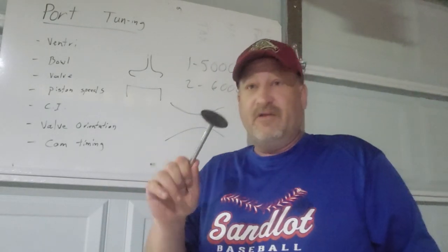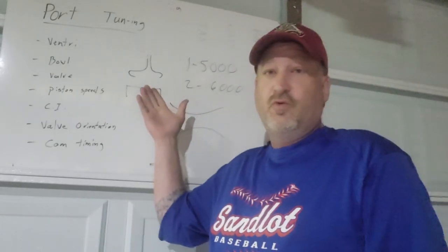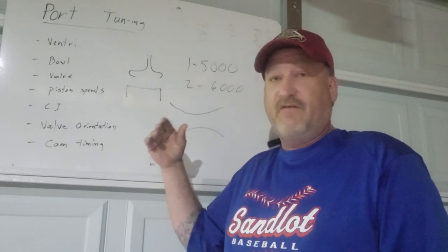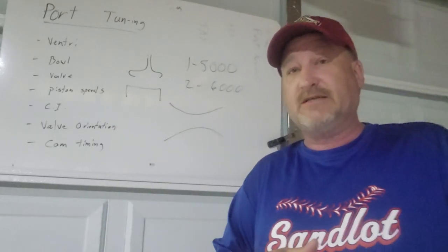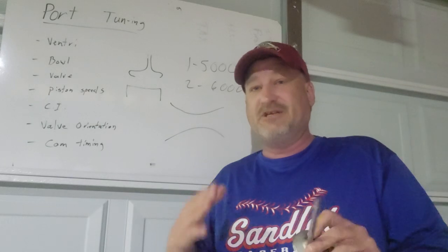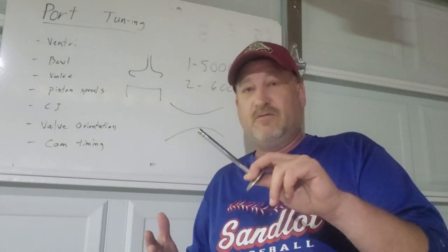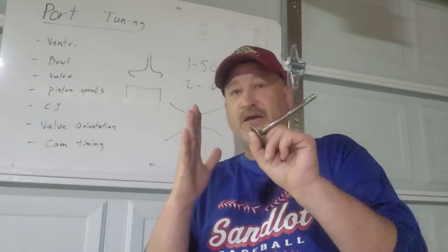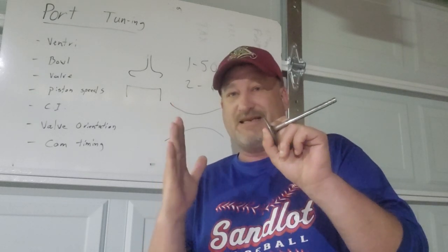So again, even little things like the cupping on the back of the valves contribute to when the reversion is occurring around the valve at each valve event and how much air is being diverted towards the exhaust. Again, with inline valves, the only orientation of the valve is directly to the center of the block. Okay, so it's going to be 23 degrees from the deck surface in orientation to the center of the block.